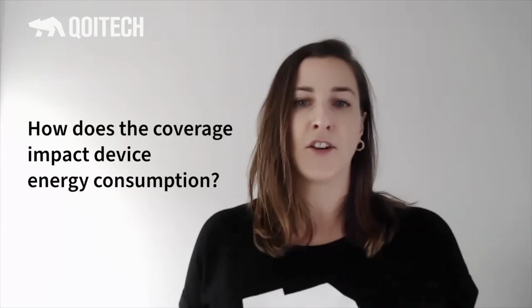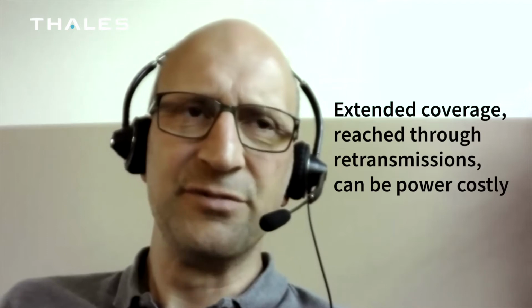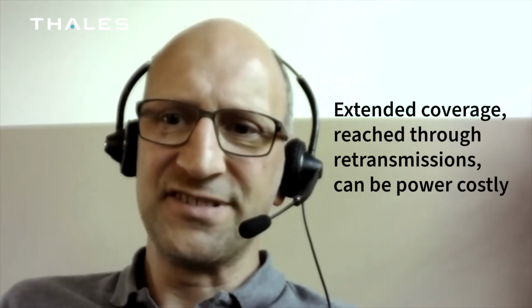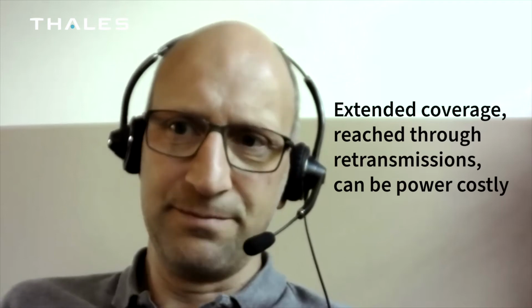How about the bicycle? Let's say, assume that it's actually out of the city, out of the coverage. NB-IoT and CAT-M offer an extended coverage anyway, where the device is doing retransmits of the data to get over these bad coverage scenarios. But depending on the protocol behind, retransmit may be confusing for the protocol, or maybe cause additional retransmissions, which cause more energy consumption finally.